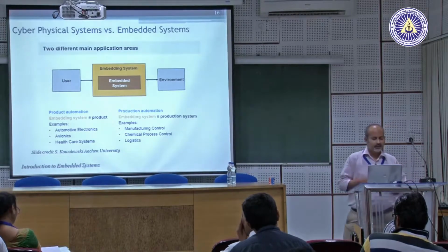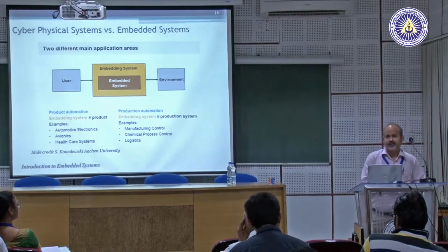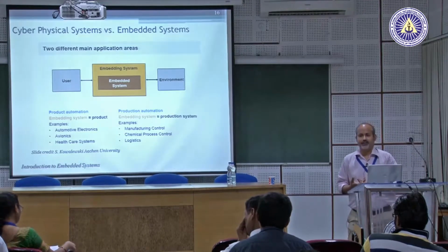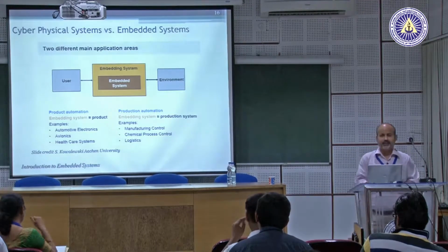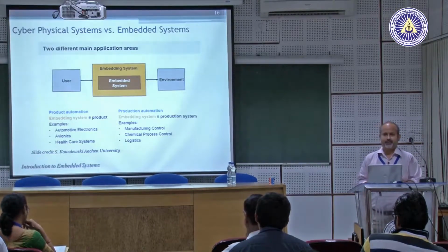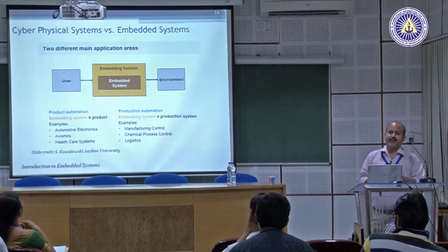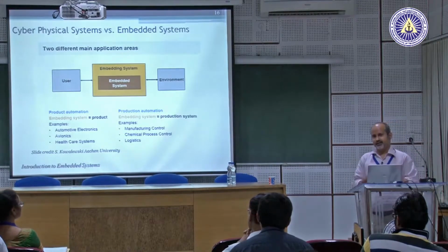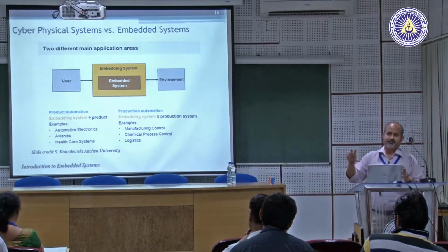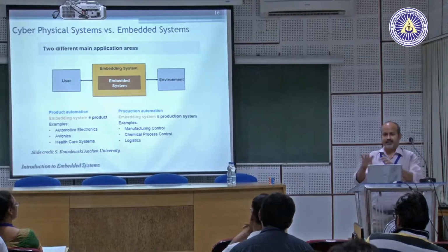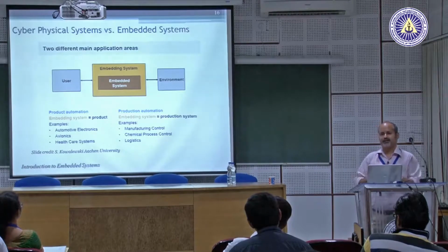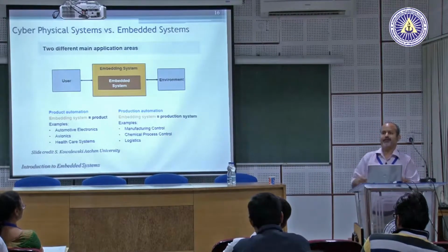Calcutta has a load dispatch center for the eastern region. For the northern region, the load dispatch center is in New Delhi, and so on. These dispatch centers are actually main control centers where all the sensors send their data, and this data is aggregated in order to compute the current state of the system. Each regional grid has its own state being estimated, and then accordingly control is done. Currently this control is not closed loop, it's a human-in-the-middle closed loop, right?